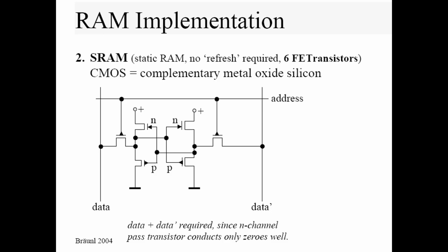As per the advantages of 6T SRAM, we have speed, stability, and low power. Speed: fast read and write operations due to the direct connection of the bit lines to the storage nodes. Stability: the cross-coupled inverters provide strong feedback, ensuring data retention. And low power: it consumes less power compared to DRAM as it does not require refresh cycles.